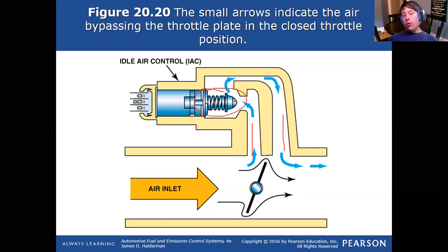On your OBD2 cars, this system came out like in OBD1. Technically, there were variations of idle speed control on your computer controlled carburetors, which were the very, very beginning dinosaurs. They were not even computer controlled. They were literally just a temp sensor, and it allowed positive power to hit this thing in order to kick the throttle up a little bit until the engine warmed up to help with carburation.